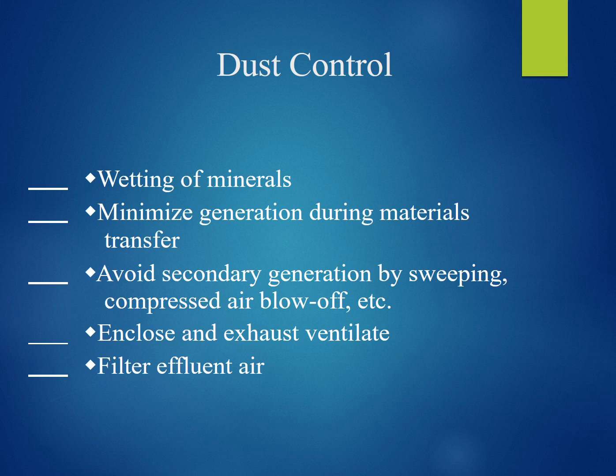Dust control can be as simple as wetting the materials. For example, cutting rock or concrete can be done with a wet saw and all but eliminate any potential silica exposure to the worker. We can also use vacuum systems and local exhaust ventilation systems to remove dust at the point of generation. Avoid dry sweeping or using compressed air to blow down equipment or clothing, as this entrains a lot of dust into the air.